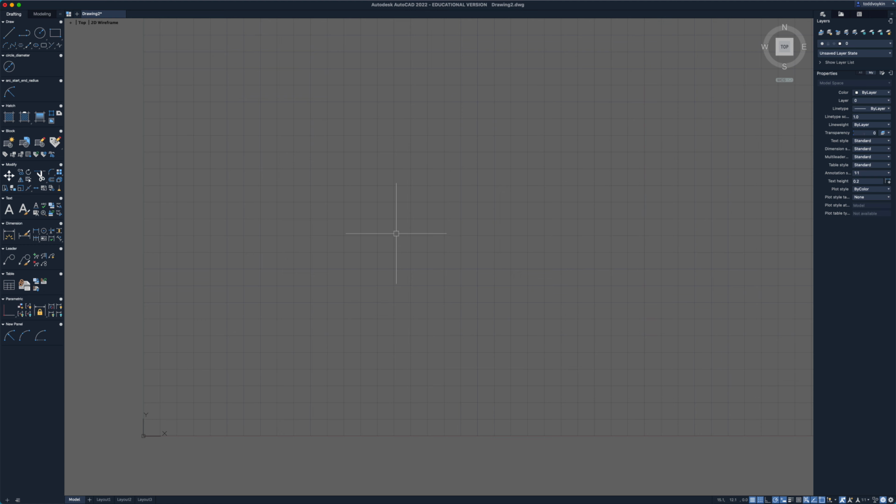Now our grid extends too far to the right and too far above. You can use just your mouse wheel to zoom in and bring that into the center of your screen, and there you have that. Okay, now if for some reason it wouldn't zoom all the way back in, you can type REGEN ALL, and that will allow you to zoom a little bit more.